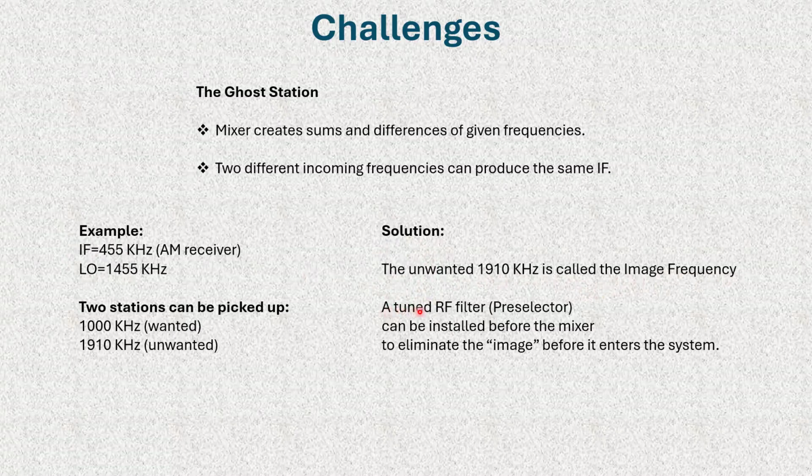Well, a tuned RF filter or preselector can be installed before the mixer in order to eliminate the image frequency. And those are far enough apart that the image can be eliminated and only this one kept. There's a problem, there's no problem.